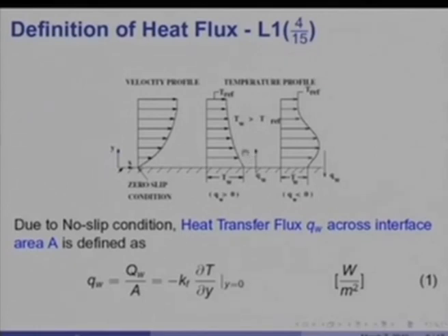Heat transfer, however, would also take place in another way, in the sense, although TW here is also greater than Tref, we shall encounter situations in which the fluid temperature close to the wall is greater than that of the wall, in which case the heat transfer would take place to the wall, although the wall temperature is bigger than the free stream temperature. So, I have shown here both the cases of positive heat transfer as well as negative heat transfer.